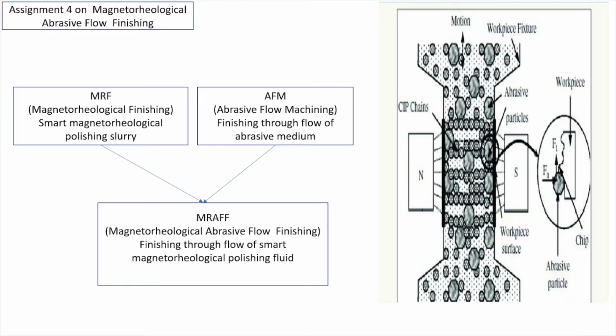So polishing of the workpiece surface begins at the lowest position of the workpiece which is to be machined, and that can be positioned fully automatically. Nowadays it is positioned in a fully automatic way to save computational and operational time. So this targeted material removal enables local correction of shape errors. In this way the whole magnetorheological finishing process basically works.